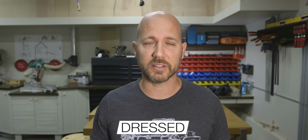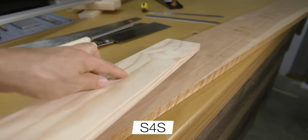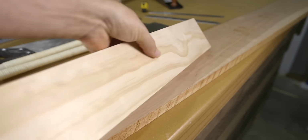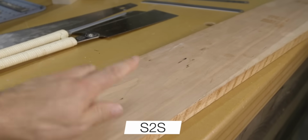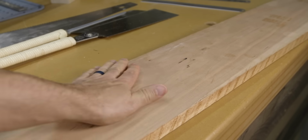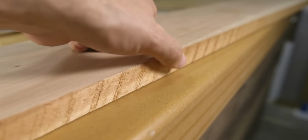Once the lumber does get sized down, it's called dressed lumber. That is, lumber that has been sized and shaped and smoothed to a nice flat surface. For example, S4S, which stands for surfaced on 4 sides, is lumber that is found at most big box stores. It's dimensioned and finished on 4 sides, ready to use. There is also S2S lumber, which is surfaced on 2 sides. Both faces are planed, but as you can see, the edges are still raw and rough.